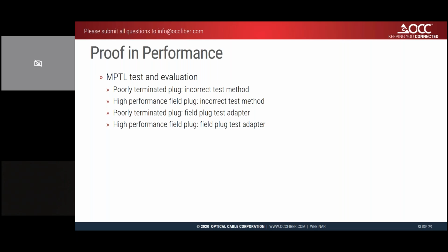So we did set up some testing to kind of prove what's going on, and that testing included making an NPTL and then making it with a very poorly terminated plug and using the incorrect test method, and then swapping the poorly terminated plug for a high performance field plug and running the incorrect test method. And then back with the poorly terminated plug using a field plug test adapter, which I'll talk to you about in just a few moments. And then also with the high performance field plug with the field plug test adapter.